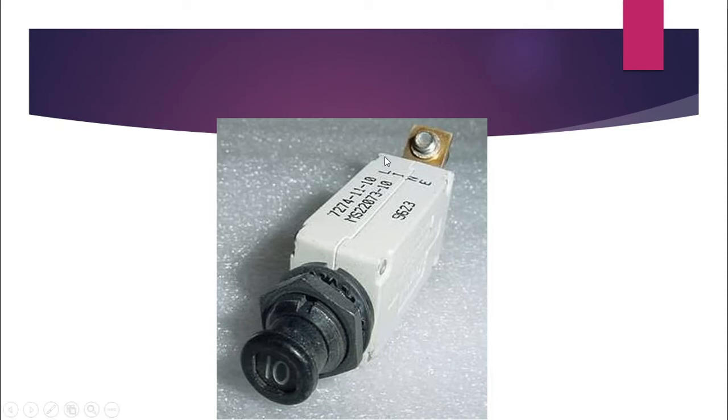So if you've got a system, let's say your communication radio inside the plane, you don't want too much electricity going into that radio, otherwise it's going to melt, fry, maybe even cause a fire in the radio, and fires in planes are not good. So a circuit breaker will automatically pop and break the circuit if there's too much current passing through it.